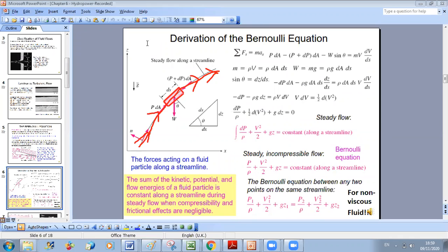If you are a mechanical engineer, you know that for certain applications, we take Reynolds to be turbulent above 2300. So if I am in a zone where I am close to 2300, even if I am in laminar zone, I still have the inertia that is dominant over viscous effects. So I still can apply Bernoulli equation.